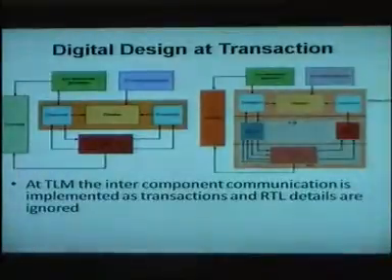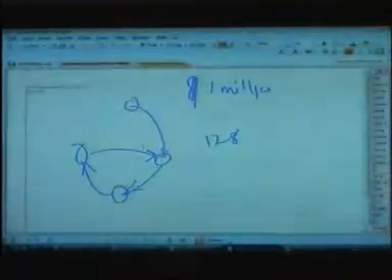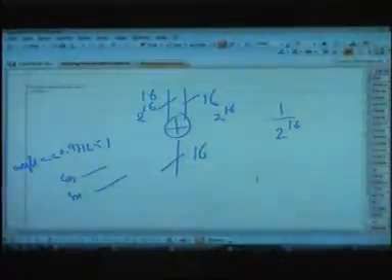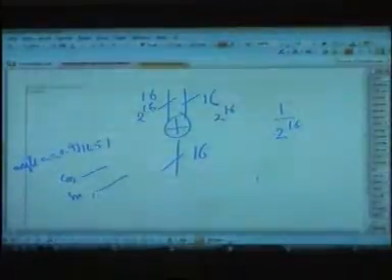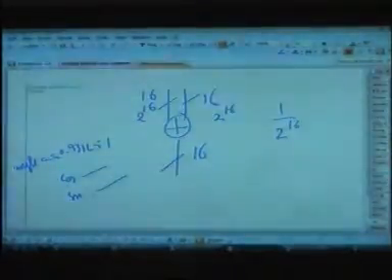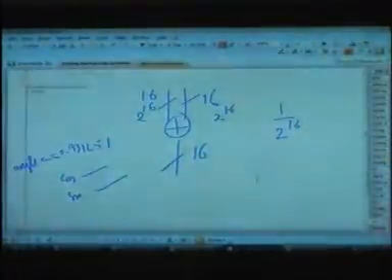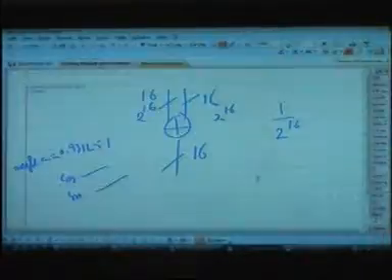For example, here I just created one where you are just adding numbers, and I'm saying, oh, you are adding, it means 2 raised to the power 16 into 2 raised to the power 16. But usually in a design, you have so many inputs. Let's say you have 16 16-bit inputs. A 16-bit input means its possibilities are 2 raised to the power 16, 2 raised to the power 16, 2 raised to the power 16. So it becomes so many that it is humanly, or even for any machine, impossible to do exhaustive testing. Then you have to be intelligent.